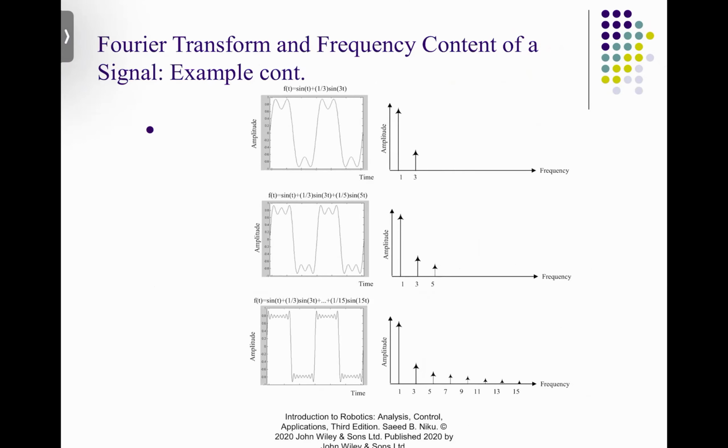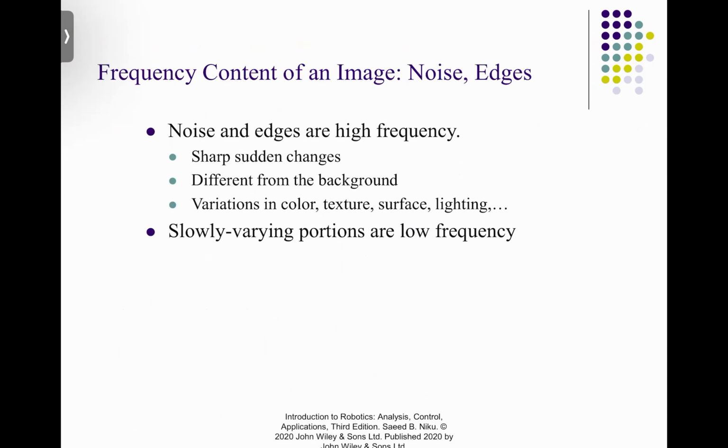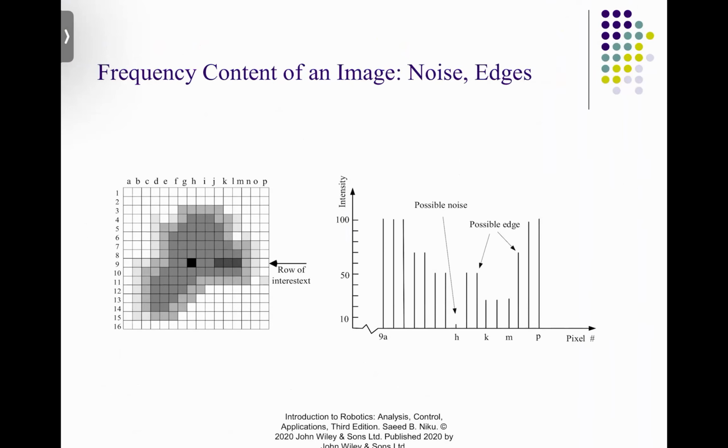We also talked about aliasing, which means if you sample incorrectly, then spurious frequencies or spurious image signals appear from that sampling, and you want to be careful about that. That's why we have something called the Nyquist criteria. But nowadays there is a concept called compressed sensing that allows you to violate the Nyquist criteria.